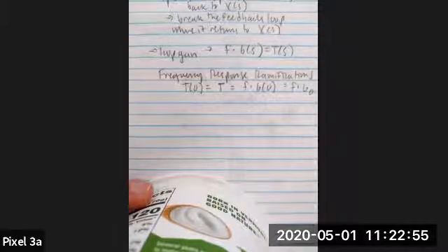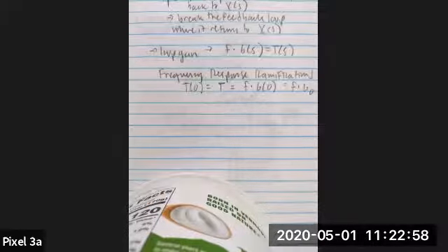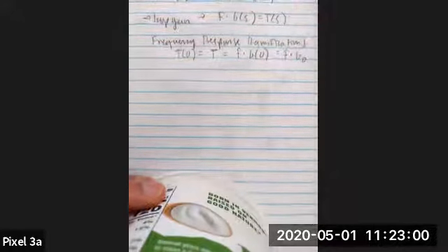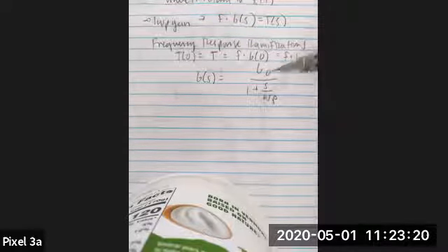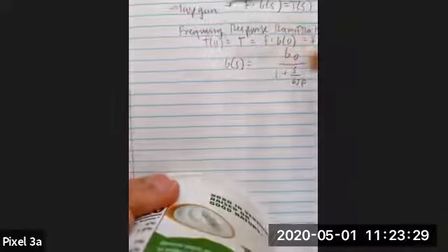So if we assume, and this actually tends to be the case, that the core amplifier has a transfer function dictated by something like this, G naught over 1 plus s over omega p. In this case, this is a single pole settling system, and it has some DC gain, which will usually be quite high, and then at some frequency omega p, we see a drop off in the gain.